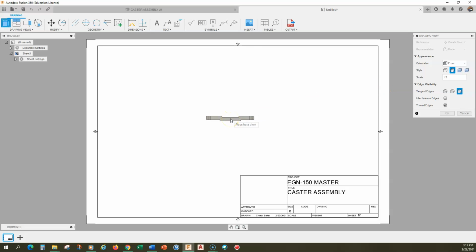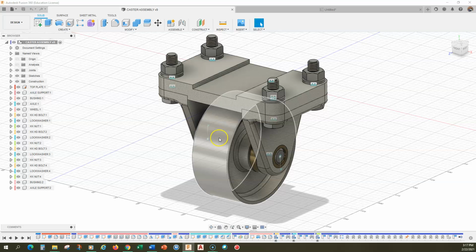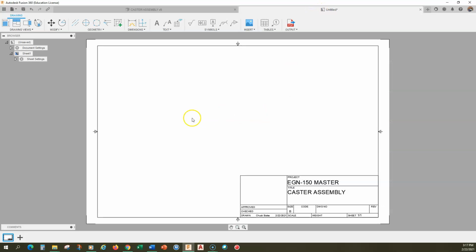Okay, now, what front view is that? That is Fusion's front view. That has nothing at all to do, necessarily, with the orthographic view that I choose as my front view. It may be my front view, or it may be my top view. Okay, but understand that the word front here is purely derived from this model and front on the view cube. So that's completely arbitrary. All right, that's completely arbitrary.